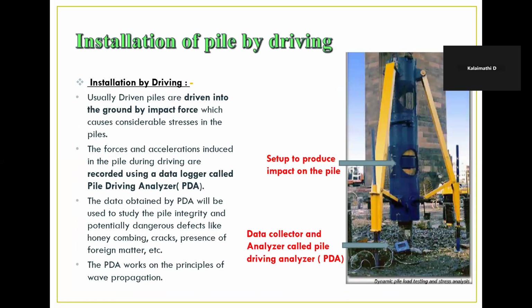driven piles. Usually, driven piles are driven into the ground by impact force, which causes considerable stresses in the piles. The forces and accelerations induced in the pile during driving are recorded using a data logger called pile driving analyzer, which is nothing but PDA. See, in this picture, the PDA is placed at the utmost bottom of the pile, which records the data and how much depth it has gone through the ground.